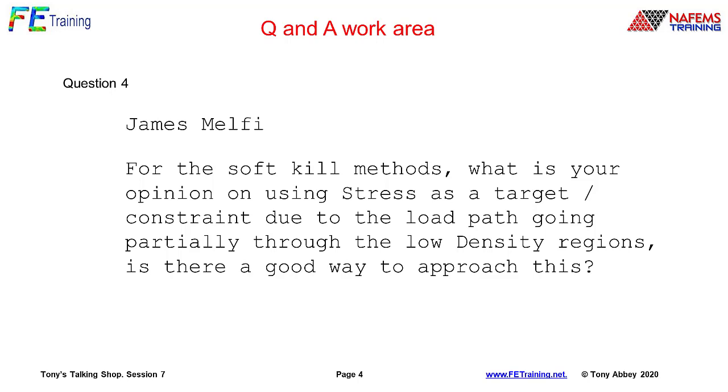What you can do is to check designs, you can take the geometry which has been implied. So again, there are many techniques. We saw, for example, Solid Thinking has one approach. CogniCAD has another approach to basically backfitting geometry through these transition regions, and then either approximating the stresses through there or getting more accurate representations of stresses. So you've got to take that transition from what you're given with that fixed, kind of clunky mesh to your interpretation and reinterpretation, maybe through geometry, maybe through remeshing, to get to a better stress representation. There are lots of different approaches we can take there.